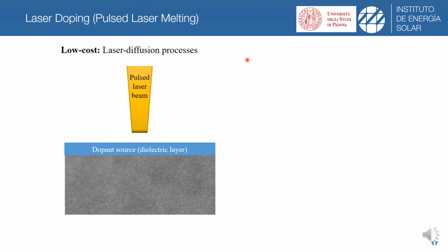So in case of having a substrate, in this case germanium, covered by an overlying dopant source, together with or alone with a dielectric layer, let's assume here the presence of a dielectric layer. After laser irradiation of this sample, when using energy fluences above a certain threshold, melting of the semiconductor takes place, and the dopant source and the dielectric undergo a phase change.